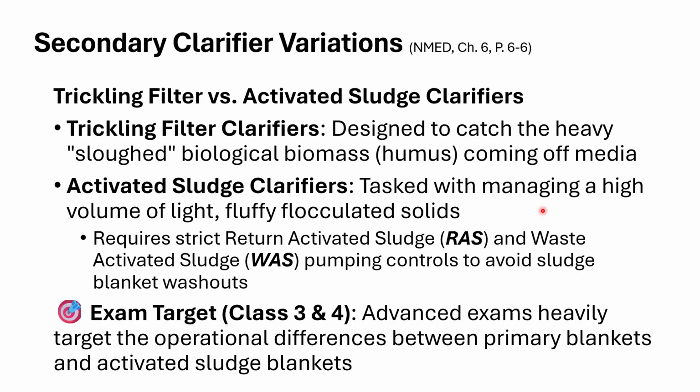And what we're doing is, in the inlet of the secondary clarifier, we are taking activated sludge that we've pulled off that sludge blanket that has organics and a lot of microbes in there, and we're returning that to the inlet or influent, mixing it with the influent of the secondary clarifier. So we're spiking it with hungry microbes. That's return activated sludge, or RAS.